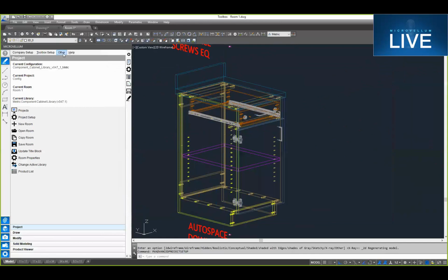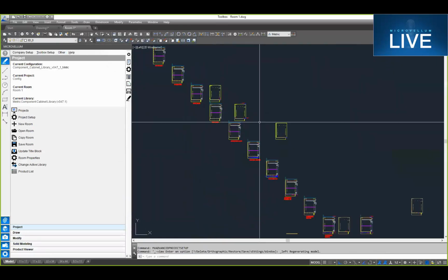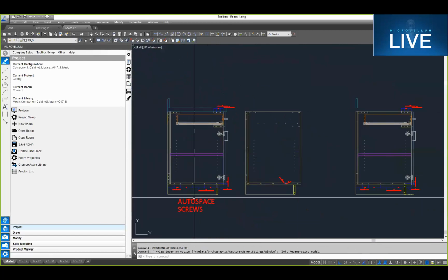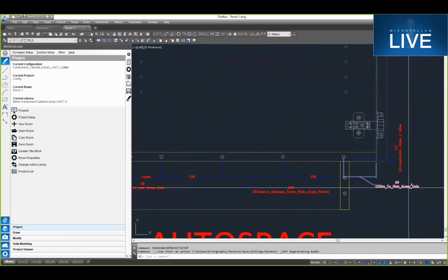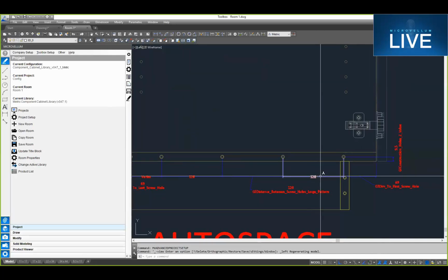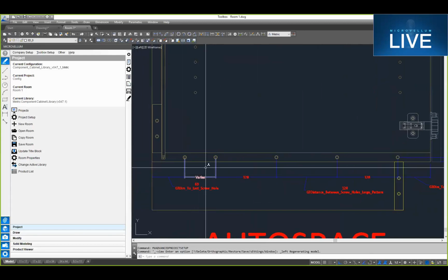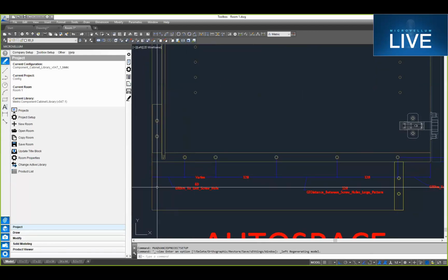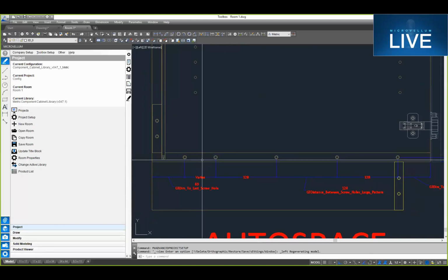So when we look at the side of our cabinet here, if we look at our dowel spacing, this one is the screw spacing, but same sort of thing applies. We have a distance to the first hole, and then we have a fixed dimension that we specify, and then this last hole is going to vary. And so we have a distance to the last hole from the back edge, and then this last spacing is going to vary.